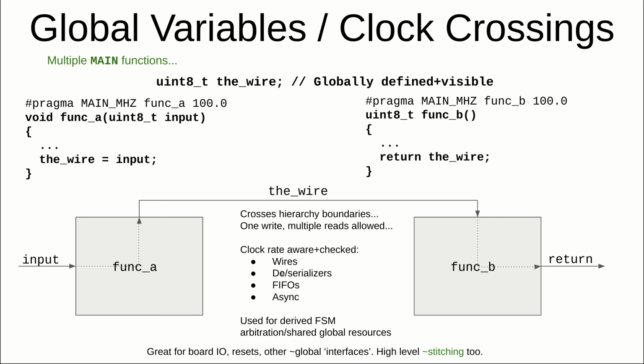And to talk about clock domain crossings here, what you get if you're going between two main functions with an integer ratio frequency that are coming from the same PLL sort of deal, you can get deserializers inferred where, if one's 4 times faster than the other rate, one's got a 4 times wider bus than the other to keep a flow of data across the crossing there.